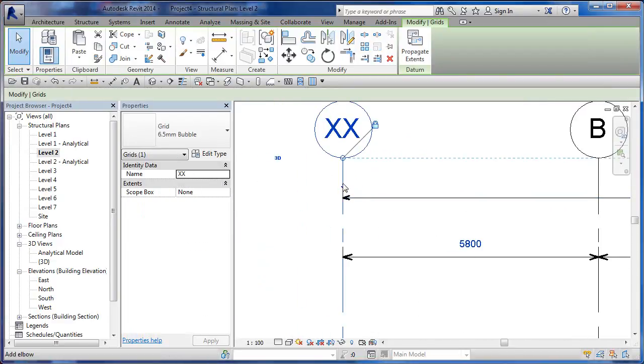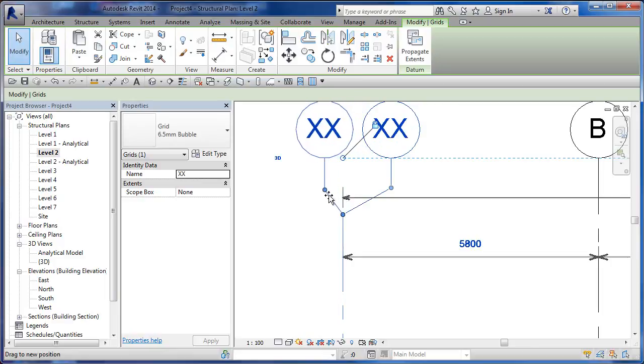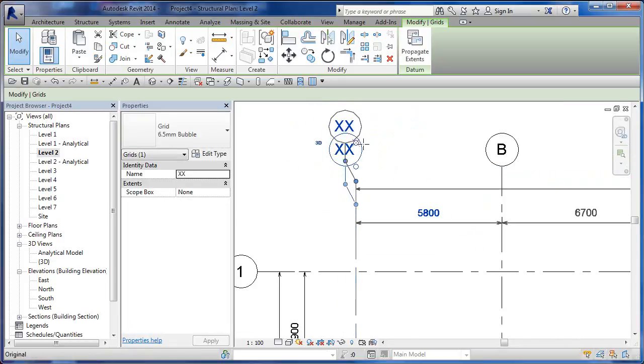And then the last thing that we've dabbled with the level lines and we kind of touched on here is if you pick on here and you hit the little break or squiggle button, it creates a dog leg, and then from there you can grab these guys and kind of move them around. You can grab these grips and move them here. So there's the grip, which is the end of the grid line. Okay, the 2D or 3D point. I don't need to say any more about that. It's just offset because of this. So if you want to bring it back, you bring it back and it heals itself.